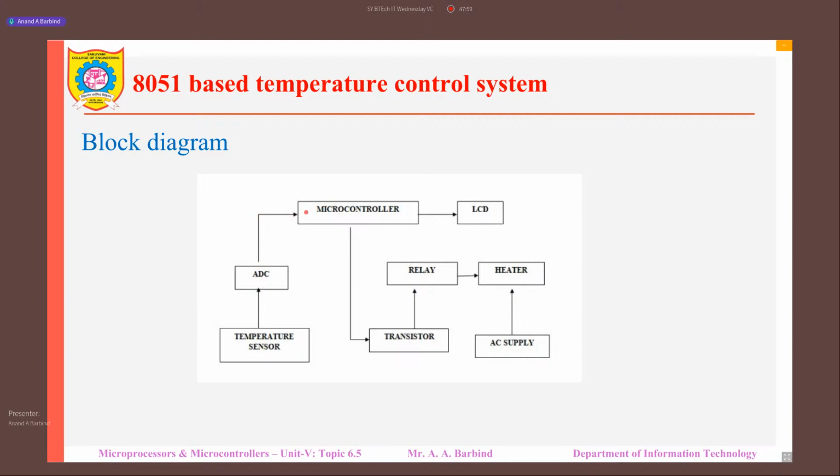Okay, so this ADC converts the analog input into digital. So what can be its output? For example, the input to the ADC is 0 to 5 volt. Corresponding to that, the output of the ADC, which is an 8-bit ADC, can be from 00H to FFH. Because it is digital, it will be in binary. Represented in hexadecimal, the output of the ADC will be 00H. That is, if the input is 0 volt, then the output will be 00000000, that is 8 times 0.